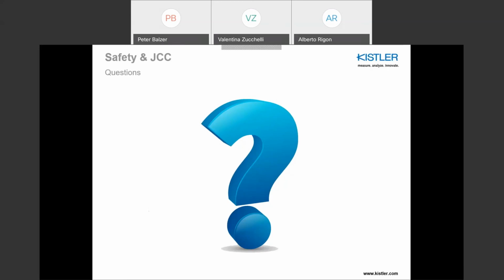And the third question was how we can write the serial number to the drive. You cannot write a serial number to the drive. You need to transfer the serial number to the maXYmos NC, because the PLC has no direct connection to the drive. Or what exactly do you mean with a serial number? If you're talking about the part ID, for example, you need to transfer it to maXYmos NC. There is no serial number available in the drive.